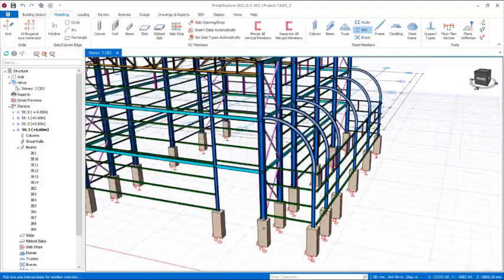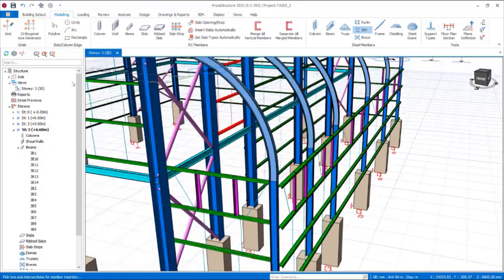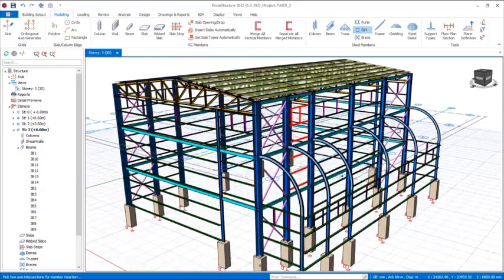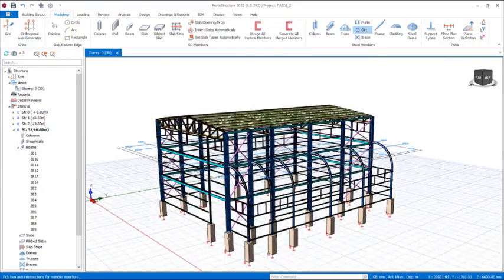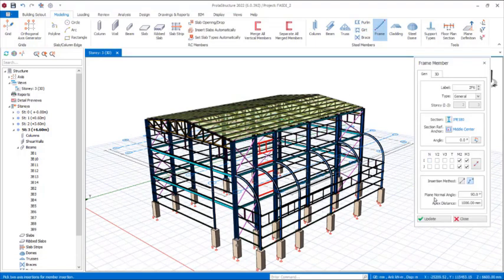Okay, so for us to be able to actually get this place roofed successfully, we need a kind of Purlins on this. So we'll be using a frame, this one, to add a Purlin on this. So you click on the frame right there. We'll be inching both ends of this frame. For the angle we'll be using a straight frame, insertion method straight frame. This one is not the curve insertion method anymore.